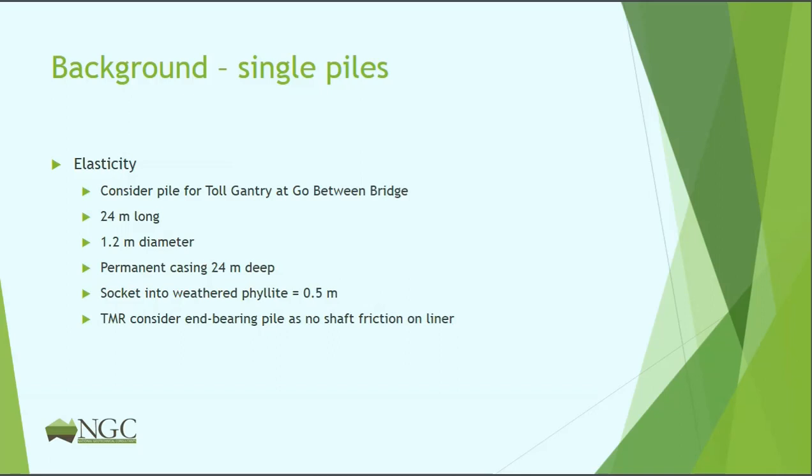Now, let's look at a single pile, and I'll take a real example. If you happen to drive over the beautiful Go Between Bridge, please have a look at the piles. I designed them. They're some of the best in the world. But on the south side, there is a tolling gantry, and that's standing on some wonderful piles. I think they're 24.5 meters long, 1.2 meters diameter.